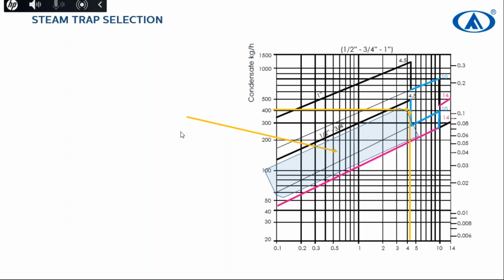It can be SK61 or TKK42, 41. It can be SK61 with high demand, high size or less size. Or for some main pure steam lines, it can be TDK71. It's also stainless steel with all spare parts stainless steel. So for beer industries, for thermodynamic, TDK71 is okay.